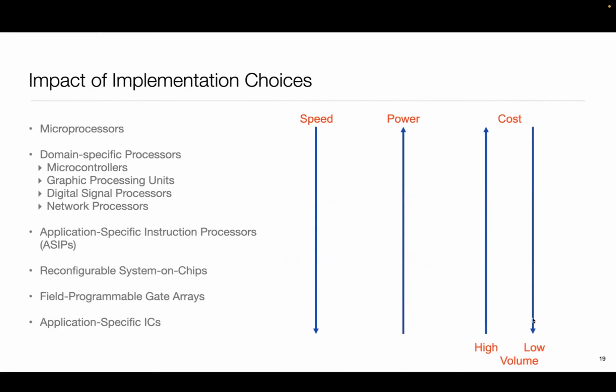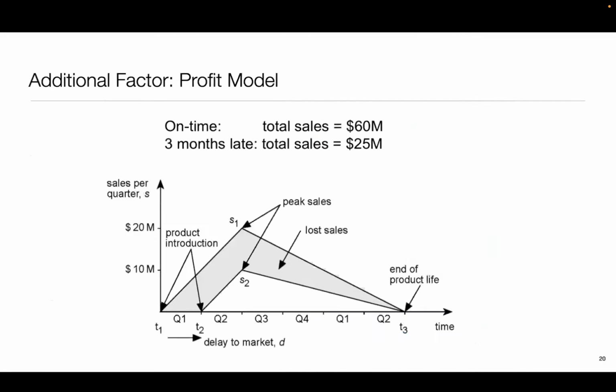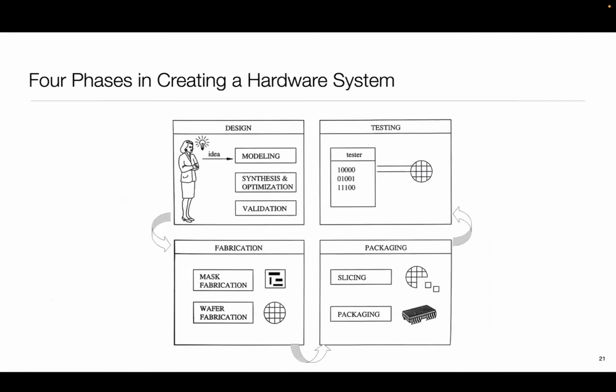There are other things out here also. There is also the time to market issue. In this industry, if you are late by a month, it may be the difference between your competitor grabbing all the market. So oftentimes you get the first iteration of your system out using an FPGA or something, even though you're taking a hit on the price structure, but meanwhile your ASIC is coming into play. So it's just a complicated technical-economic sort of game. I'm going to skip that.